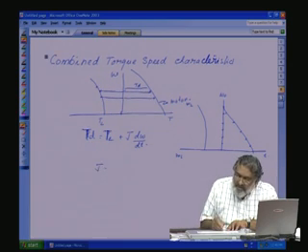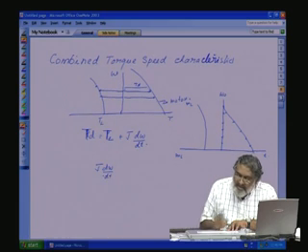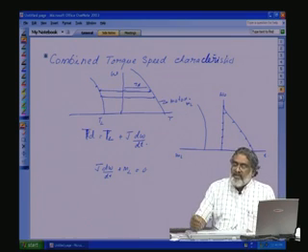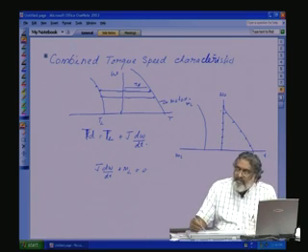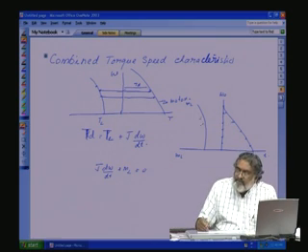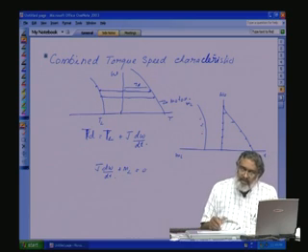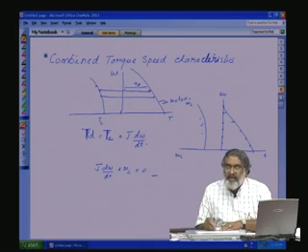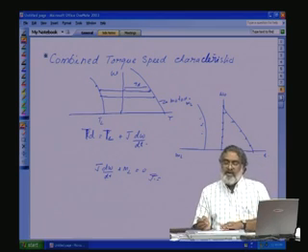If you write the equation J into d omega by dt plus ML is equal to 0, because we have switched off the system and the system is decelerating. So, at various speeds, J into d omega by dt, the decelerating torque, is the no load torque of the system, that we can get from this. So, d omega by dt we know, ML we know, we can approximately find out J. This is one way of doing the thing.